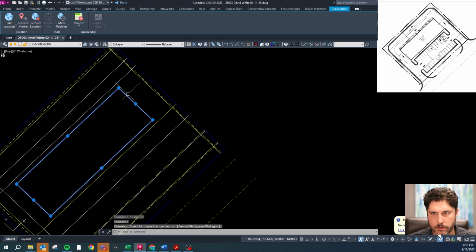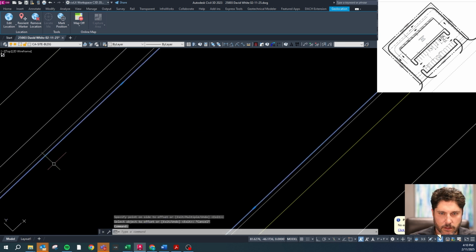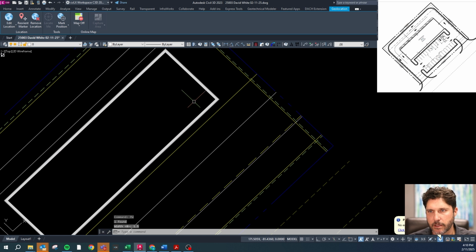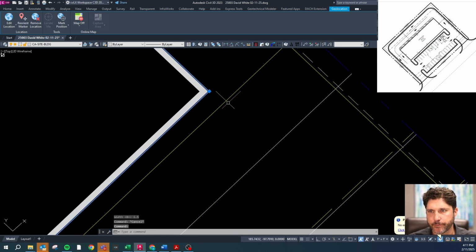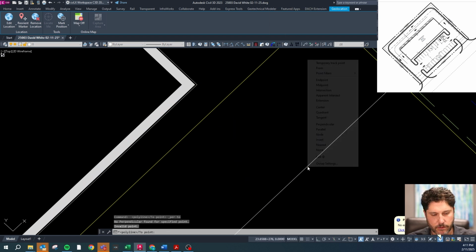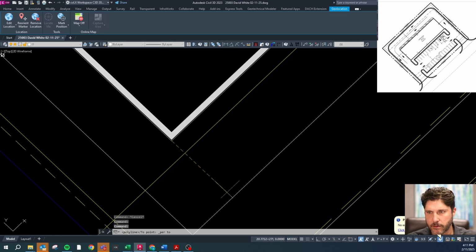And then we'll make this a polyline, PJJ. That didn't work, let's try it again. PJJ. And we'll offset that by 1 foot, and then polyline the width of 1.5. That gives us the thick line, so it looks like a thick border, but it doesn't stick out past the actual boundary of the building. Then from here, we'll come out for that curb, and we'll do the same thing here.